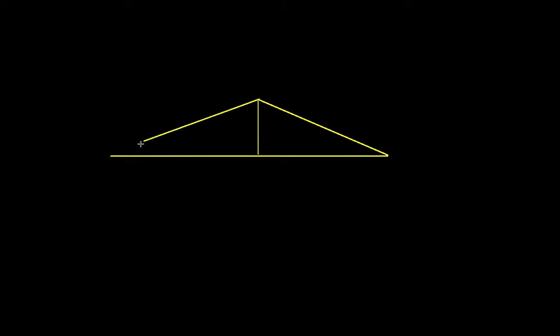The first thing I need to do is draw a free body diagram of the entire structure. So I'll just whip out a free body diagram here. Okay, there's our free body diagram. We are going to have a load, and again, we've said that the load is going to be 8,000 pounds. And we're going to have reaction forces. We'll have a force that I've called here FAY, and a force that I've called here FAX. This is from the pinned side of the bridge.